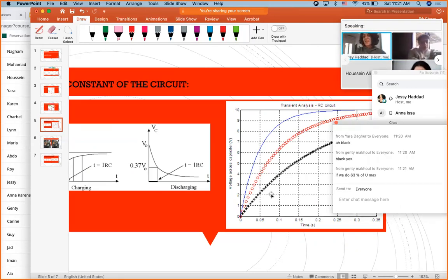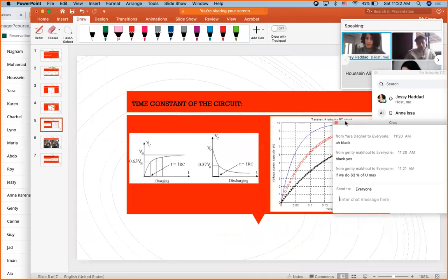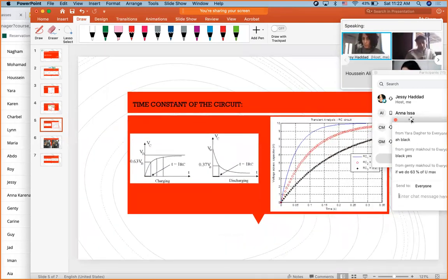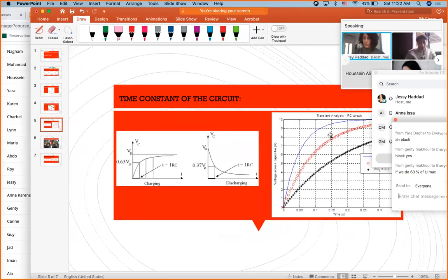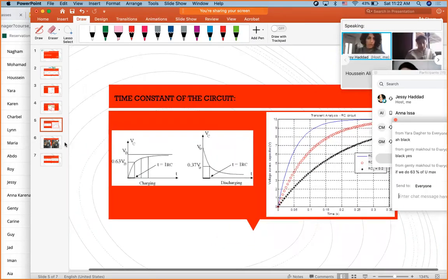Okay, so listen, this is a common mistake. When you see a fast behavior, you would think tau is big. Remember, tau is big when the behavior is slow. All right, so no need to do tangent, neither is 63%, although both methods are fine. Just think about slow and fast. Blue is so fast. Fast means a smaller time, okay? I think you guys thought fast means bigger time. So yeah, mistakes happen. So basically, this is just a behavior to see how things are actually doing.